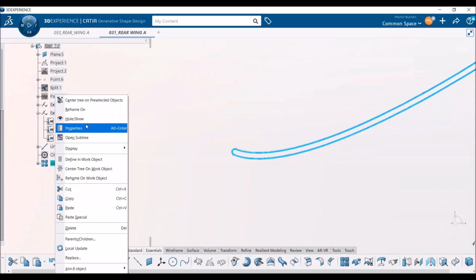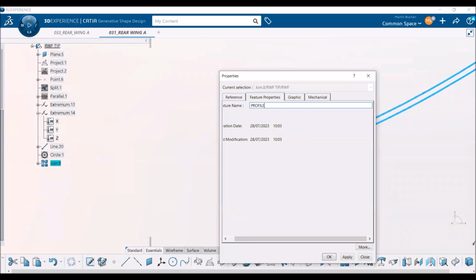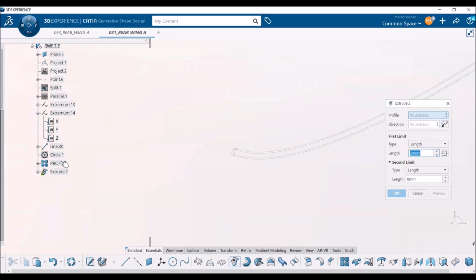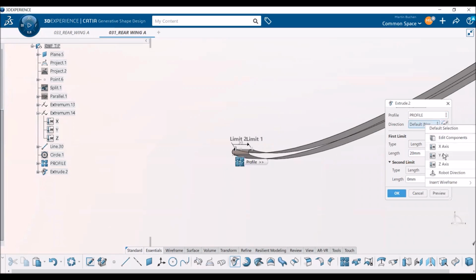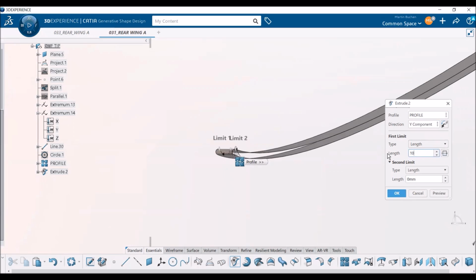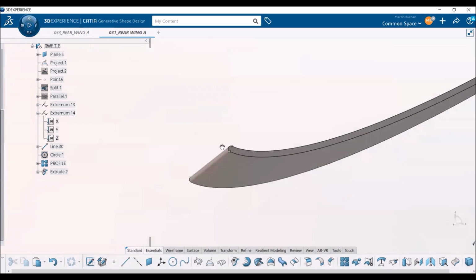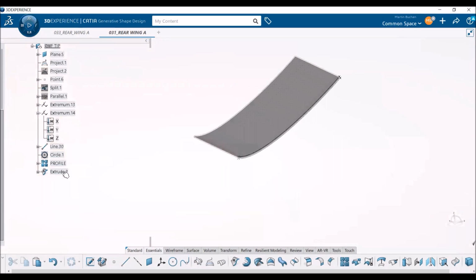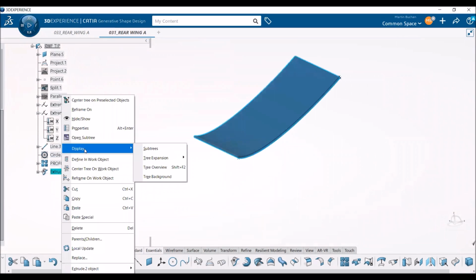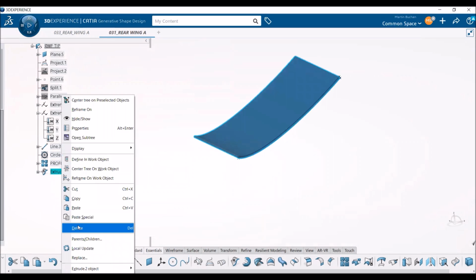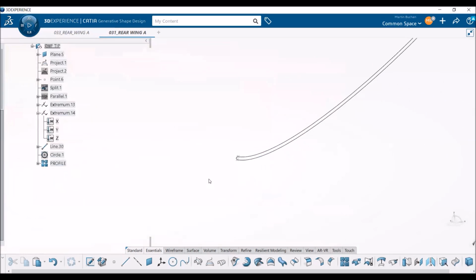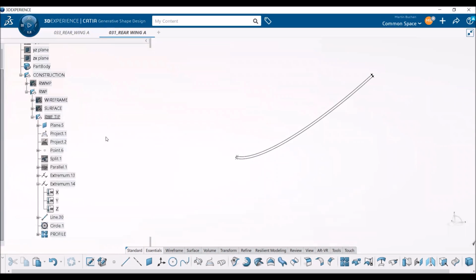So we just call it profile because for the real wing profiles, we also called it profile. So it's always profile and trailing edge. And then together it's the complete profile. So we now create an extrude of this profile, and this is how we can see that it's parallel, that it's tangent, because the lines there at the very front are gray and not black. So it means it's tangent, so it's fine. It's really a bitangent round leading edge. So the profile is fine now.